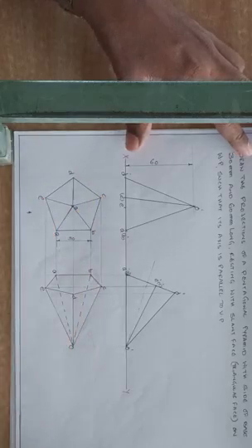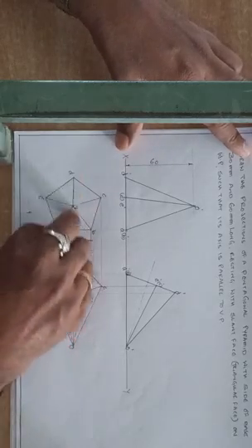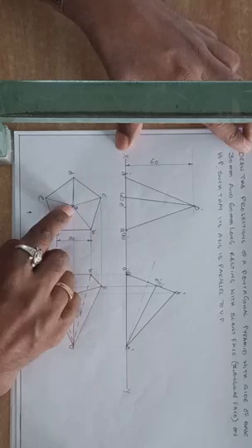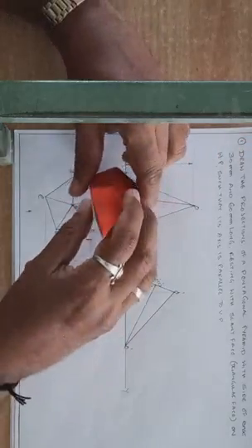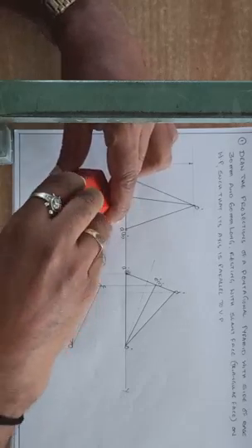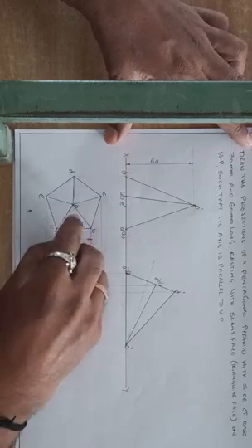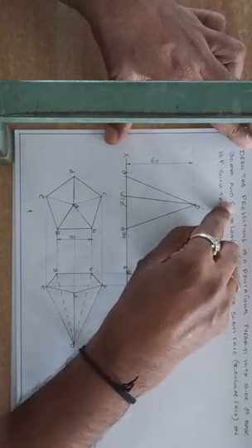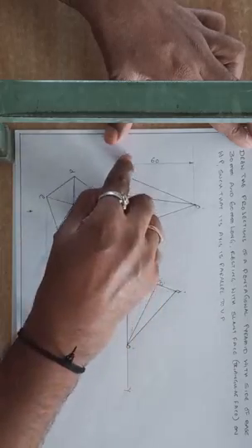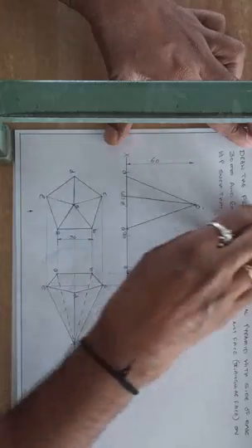Construct the pentagon. Now join all the corners with the midpoint, because in pyramids all the edges, the end generators, are visible. First project the axis line upwards, then project the points up to the reference line only. Don't project long.